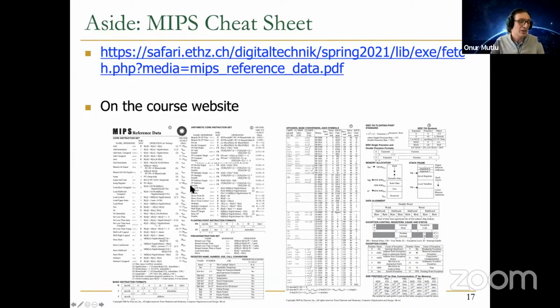You just need to follow the specification of the instruction in the ISA, add the data path elements, and add the control signals to enable the execution of the instructions, and set the control signals accordingly so that the instruction gets executed correctly and no harm is done if an instruction is not touching some parts, or some registers, for example, or memory. Okay, so hopefully now you know the methodology to really build a single cycle microarchitecture for an entire instruction set architecture. It's really not different from what we did. You just need to repeat what we did for every single instruction.